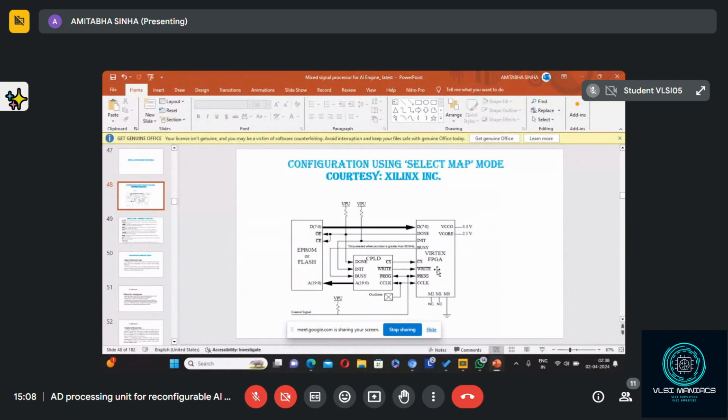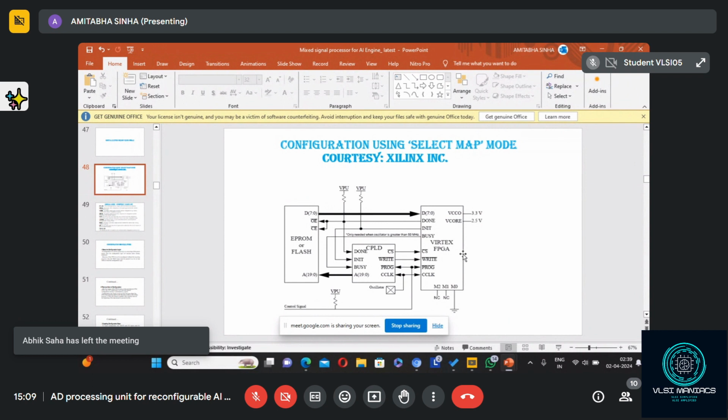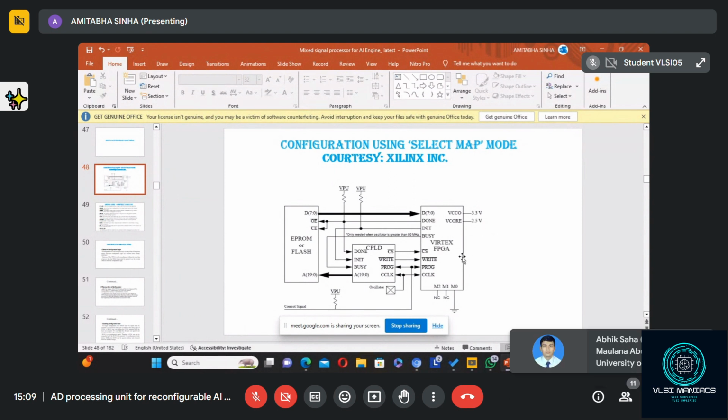There are two signals. One is write bar, one is prog bar. Write bar is to write the data onto the FPGA. That means the data D0 to D7 will be downloaded provided the chip select bar is low and write bar is low. It's a must. And there is a line called prog bar. The FPGA will work in two modes. One is the programming mode, another is the execution mode.